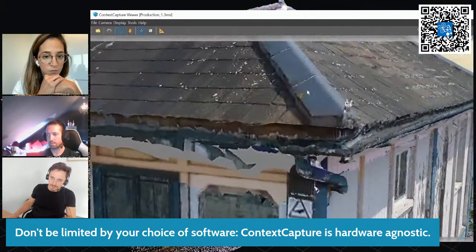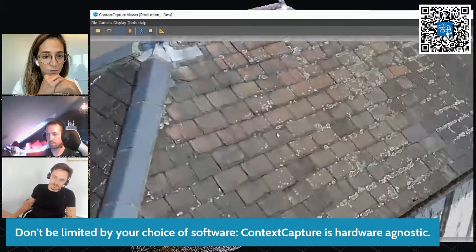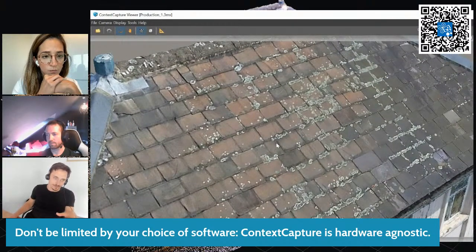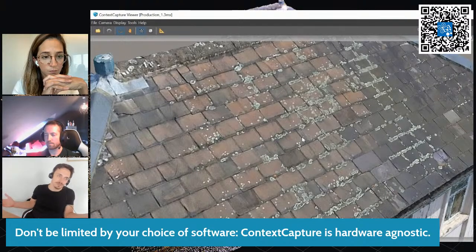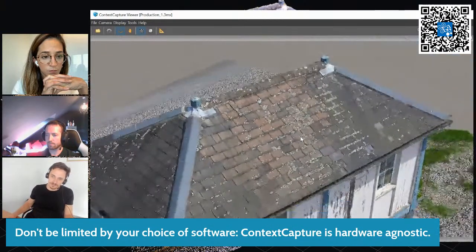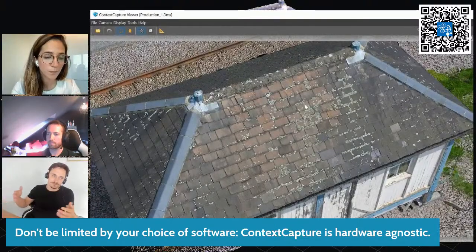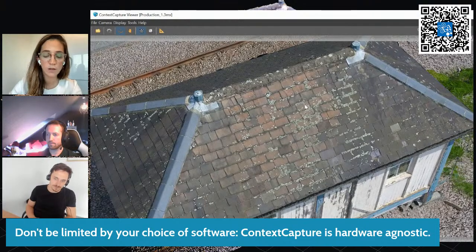with the proper texture. That could be not only about the texture, but also about some inaccessible area. If that is some tall building, you won't be able to go and scan the roof with terrestrial laser scanning, because maybe that was the highest building in the neighborhood. Actually, that was one of the major problems I met when I was a scanning specialist in the past. We tried, for example, to get a view on the roof, but then you have to find a taller building, and then you also have to use a really powerful laser scanner with a huge range.